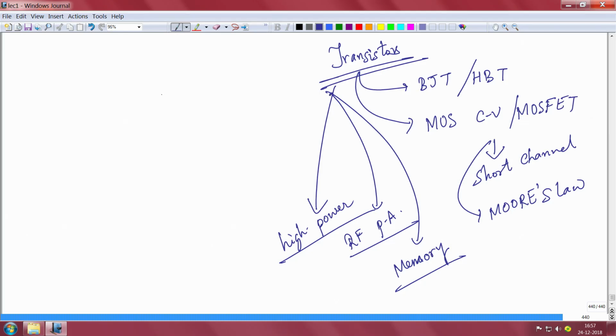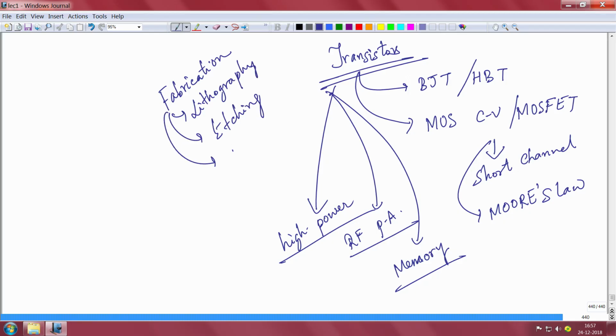And finally, I had also talked a little bit on the fabrication of many of these devices in the clean room, things like lithography, etching to make the patterns and define structures in the devices. Also we talked about deposition, like metal deposition, CVD, chemical vapor deposition, E-beam evaporation. Also we talked about things like doping, like diffusion and ion implantation and so on, right.